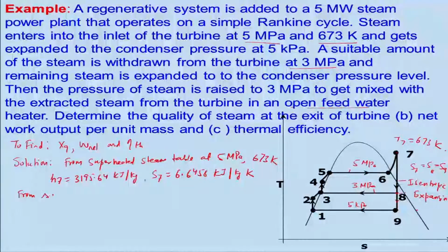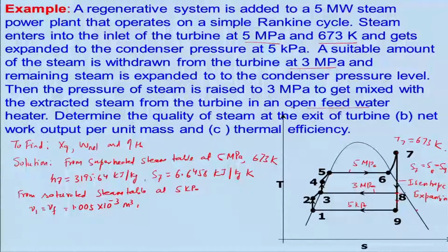From the saturated steam table at 5 kilopascal, I will get this data. V1 is equal to Vf, that is this condition, equal to 1.005 into 10 power minus 3 meter cube per kg. This is basically specific volume.